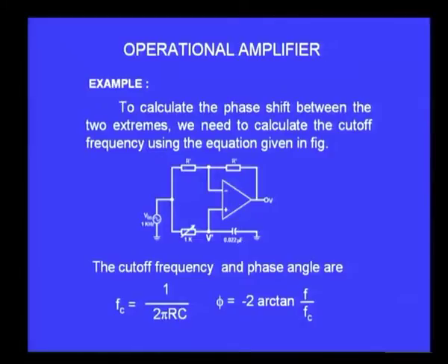So, what we have now is the same circuit with a potentiometer here, and we can shift the potentiometer from this end to that end, thereby I will be varying the phase of the amplifier from 0 to 180 degrees. The cutoff frequency for this is decided by the two resistor RC combination that I have here, and I have used here 1K and 0.022 microfarad. So, Fc is 1 by 2 pi RC.